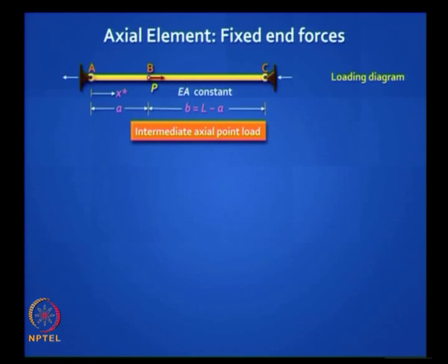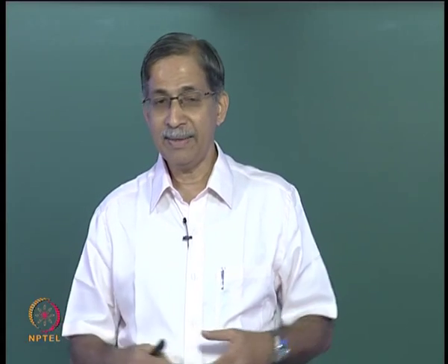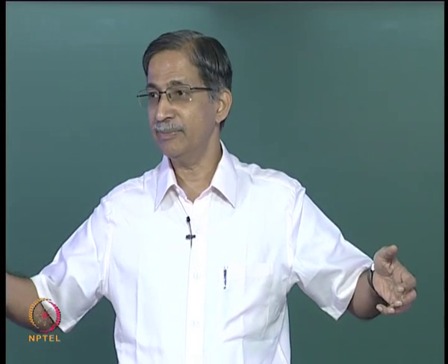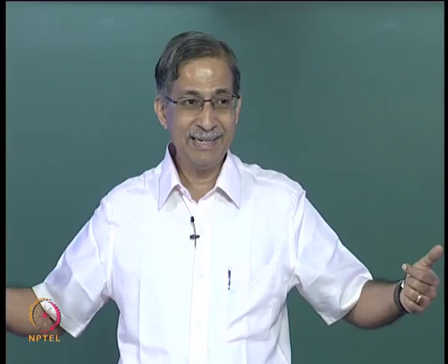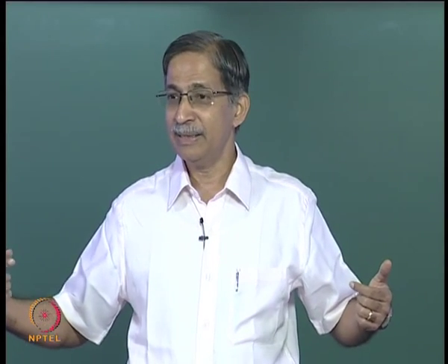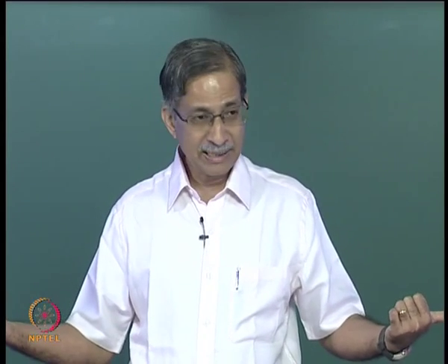Those are the fixed end forces, if you wish. What do we mean by fixed end forces? You are familiar with fixed end moments in a beam. There you arrested the rotational degrees of freedom. Here you arrest the translation degrees of freedom, and if you pull it there, you will get some reactions at these two ends.